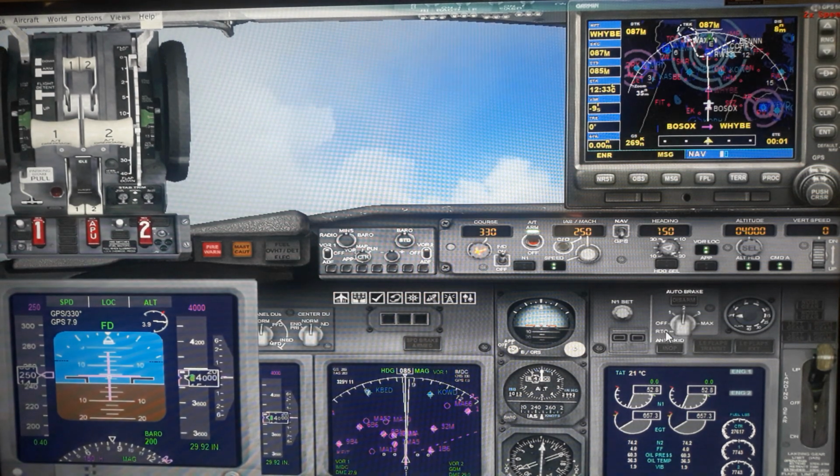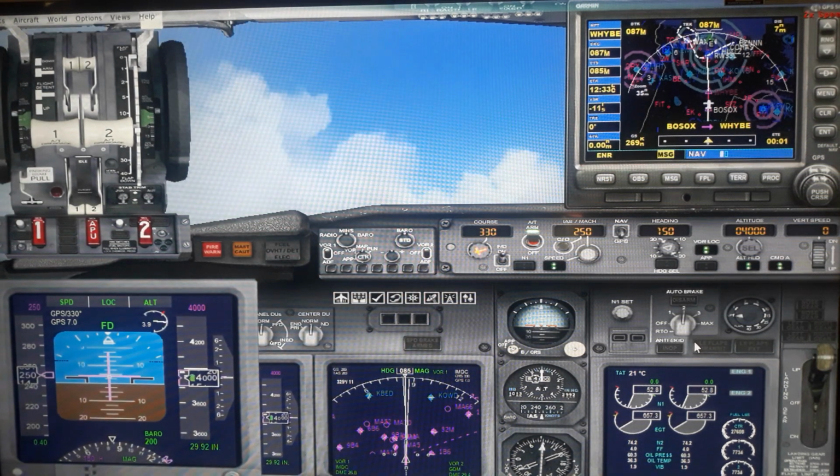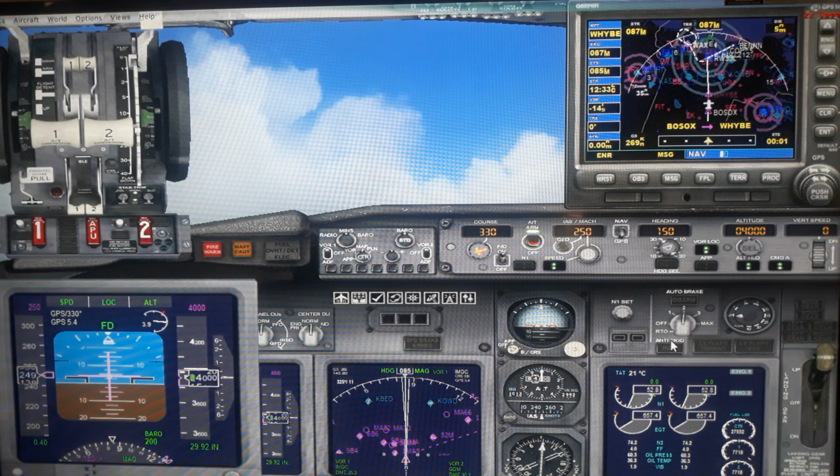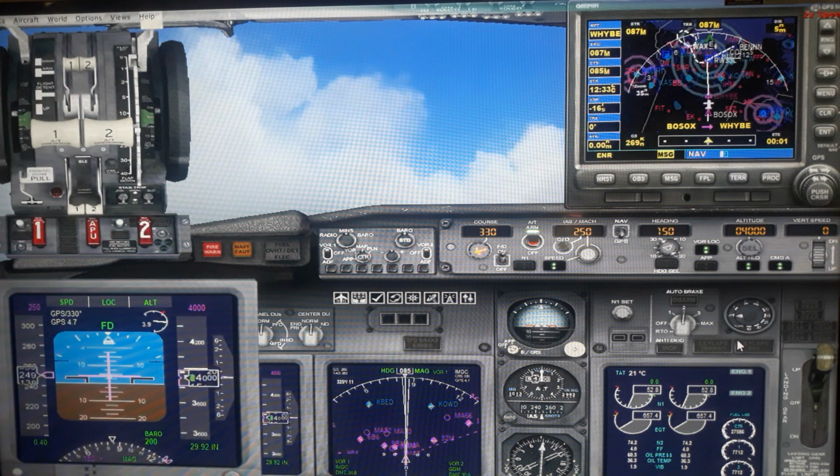We had put it on the rejected RTO for takeoff. That is, beyond V2 you cannot abort. At V1 you can abort the takeoff, and this RTO is for the heavy braking on the runway itself before we go out of the runway.